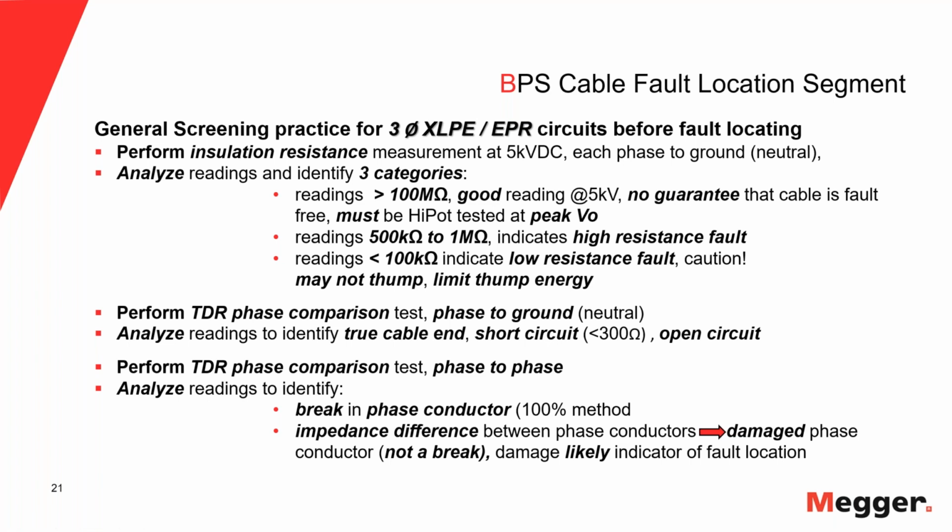Many times, somebody does an insulation resistance test, reads a reading, and says the cable is good. Well, it might be, but it could also not be. So be careful about this.